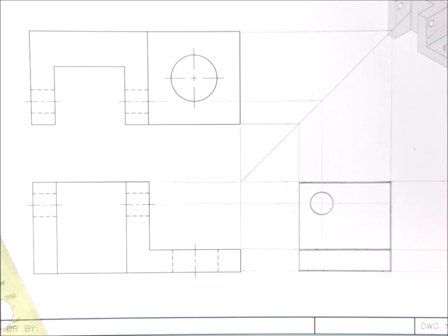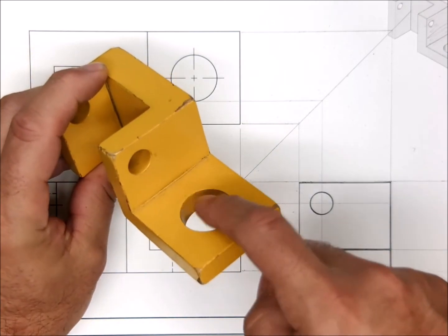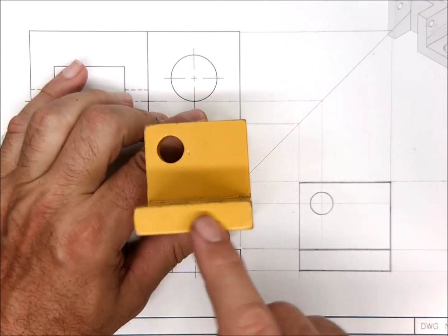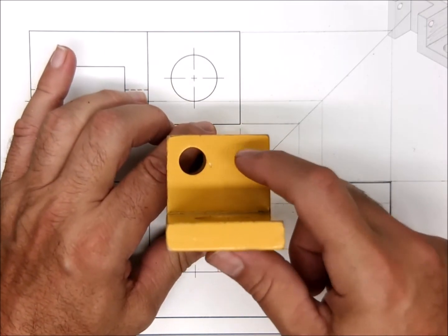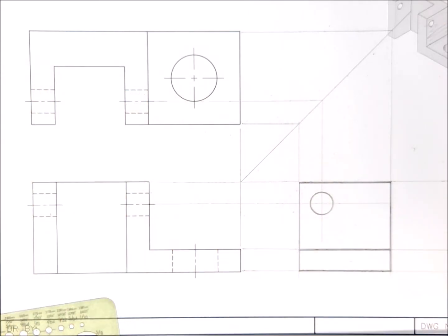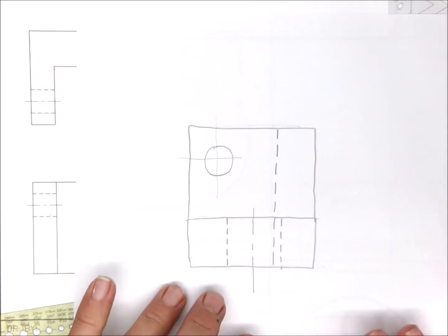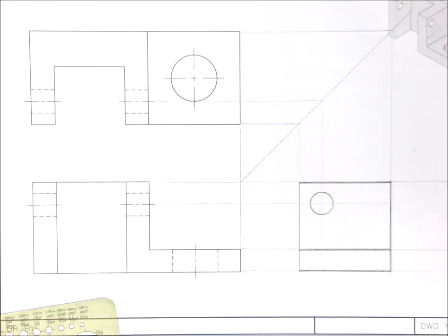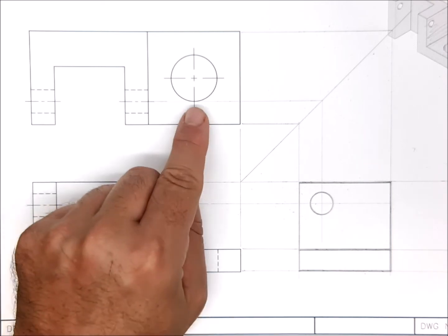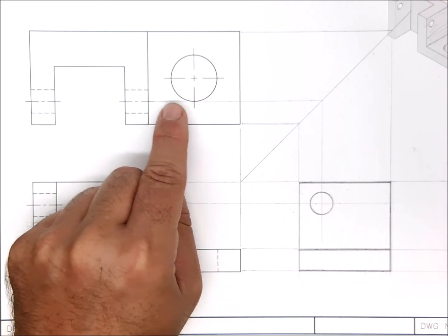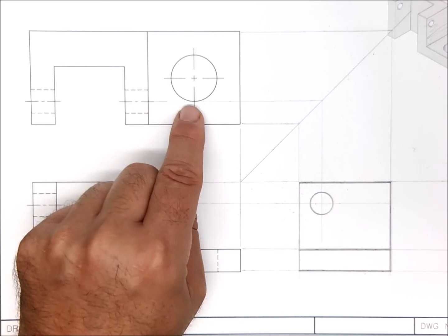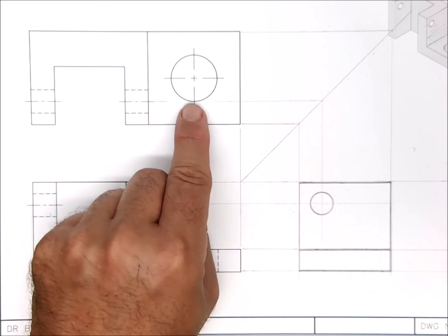Well, yes, we know some of those elements that we were talking about are hidden, right? I can't see the tunnel from this hole looking at the front edge here. It's hidden. And I can't see the edge back here looking there. It's hidden. So, again, having an idea of what I want will be helpful. Let's play the projection game, and that'll solve these for us. We take a look at the hole, it is even with the center line of that smaller hole here. So this line has already been projected over and down for the side of the hole.